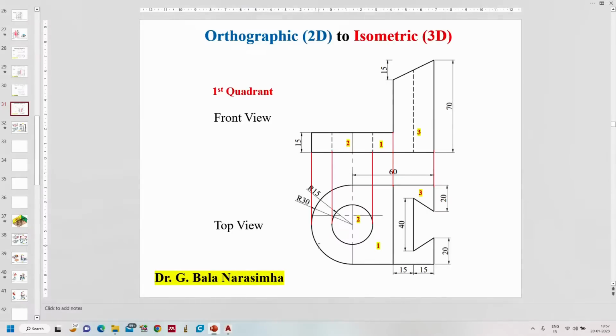Okay, now after forming this one, you can see the main difference. As I said earlier, in the previous tutorials we extruded simply 70 mm, but here the extrusion is of taperedness. The height is 70 from here, and from here some height, we need to calculate that one. See, from the top 15 and here 15, total 70 minus 30, this distance will be 40. So now from 40 to 70 there will be taperedness, so we need to remove this space.